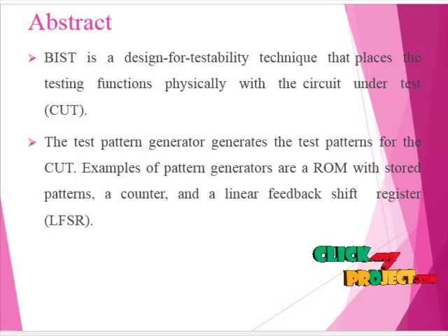We propose an LP test compression method that allows shaping the test power envelope in a fully predictable, accurate, and flexible fashion by adopting the PRESTO-based logic BIST infrastructure. The BIST is a design for testability technique that places the testing functions physically with the circuit under test. The test pattern generator generates the test patterns for the CUT. Examples of pattern generators are a ROM with stored patterns, a counter, and a linear feedback shift register.